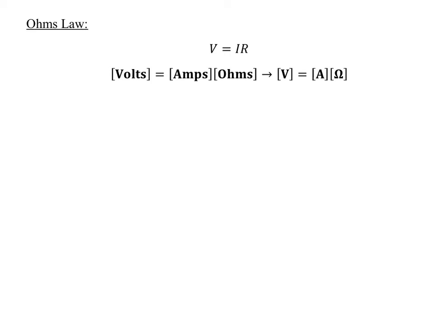So in these cases, we're recognizing that V equals IR is one of the laws we're going to use, but what is really important here is if you want to measure the resistance of something, just solve for R. Even before we had multimeters, you had to do this. If you measure the current and the voltage going across an element, you can determine its internal resistance.